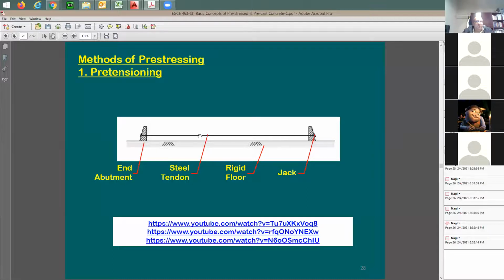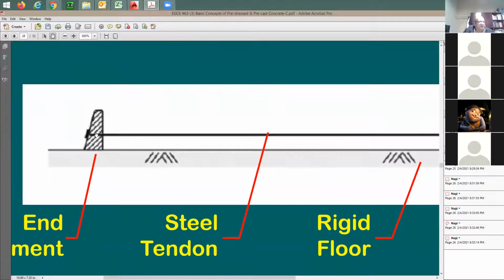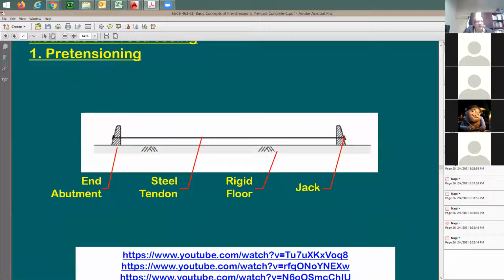Because once you start, let's say that you're going to put a jack, an anchor from here, right? This is going to be a cable, it's going to be coming with this piece, like an anchor piece. The cable is going to be this way. You're going to start to apply tension here, right? You apply tension by jacking it, right? You pull the cable. And then at a certain point, you're going to put the anchor down. Now take the jack out and you put the anchor. So it's going to happen after this.